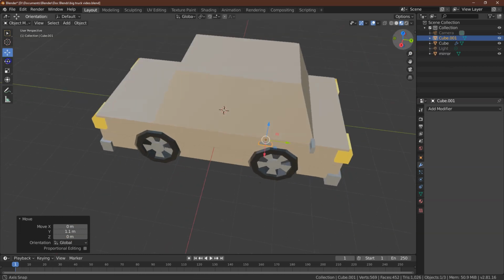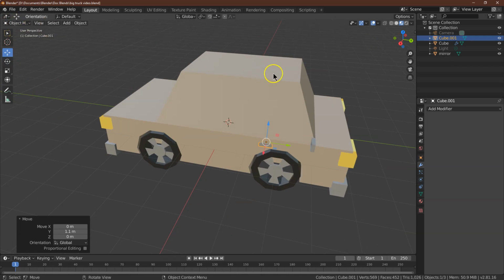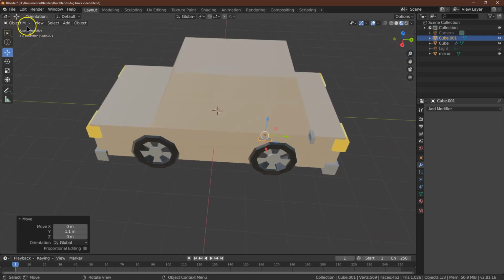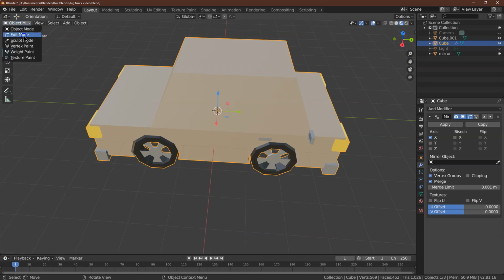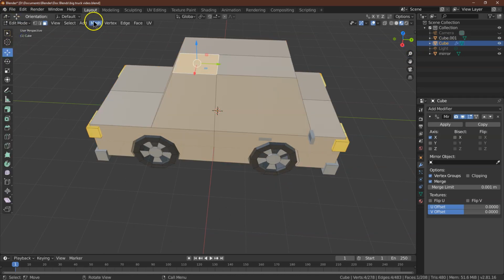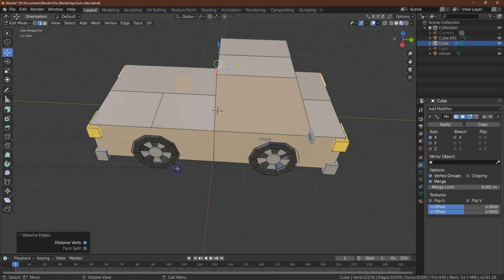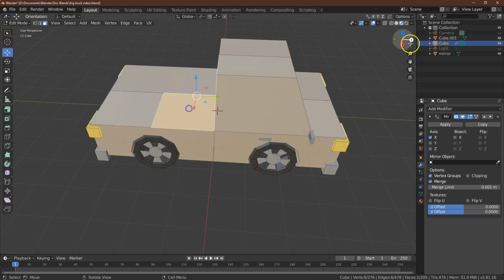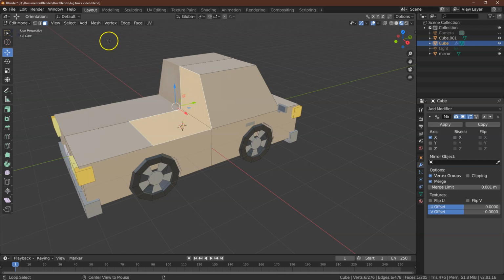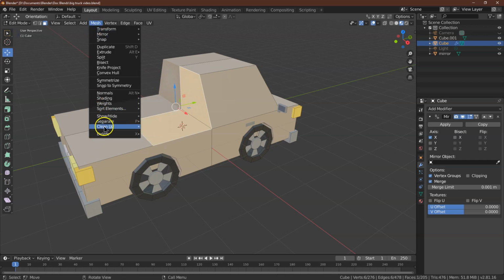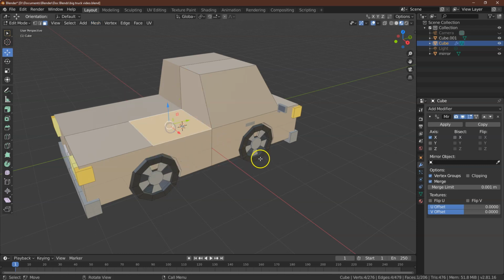And now for the back, let's go ahead then, now we'll duplicate those towards the end. Alright, so for the back, we're going to do edit, and I'm going to click on line mode, and I need this line, and I'm holding shift now, and this line. And I'm going to go ahead and do mesh, delete, dissolve, edges. And now we get this weird face thing that's right here. And to separate that back out, that's fine. We're just going to go to mesh, clean up, and split faces. Boom. And now they're separated.